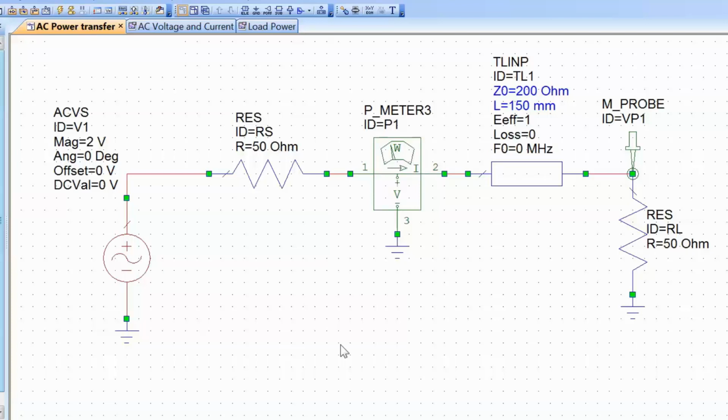So the condition for maximum power transfer when you have a resistive circuit like this operating at high frequency is that you have Rs equal to RL, but also equal to the characteristic impedance of the line. So Rs = Z0 = RL is the new condition for maximum power transfer when you're working with high frequency circuits.